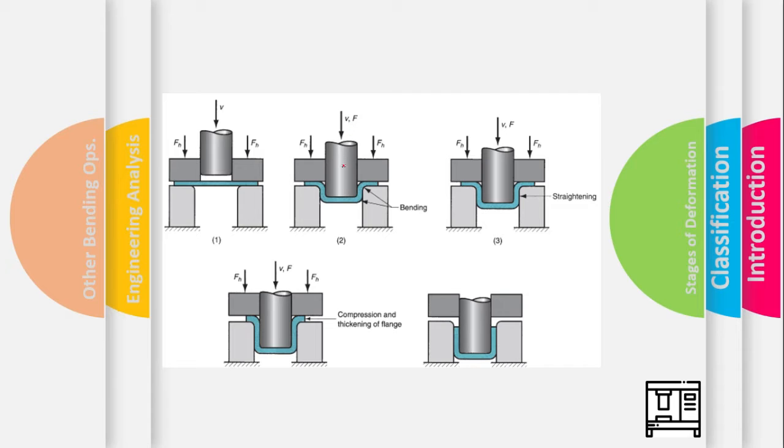So when the punch comes in contact with the blank, the first kind of deformation that occurs in the blank is the sheet metal bending. You can see here the metal is being strained along the corner of the die, along the radii of the die, by a punch and with the help of the blank holder. So the first kind of deformation that metals undergo during the drawing operation is the sheet metal bending. The sheet is simply bent over the corner of the punch and the corner of the die radii. So it is bending at two edges. We have the bending at the corner of the die and the corner of the punch here, right?